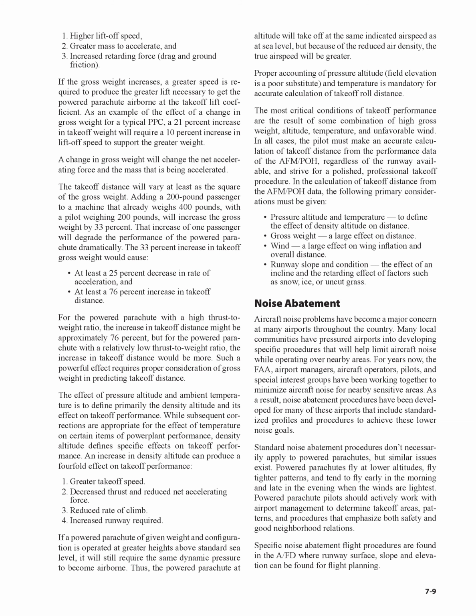roll distance. The most critical conditions of takeoff performance are the result of some combination of high gross weight, altitude, temperature, and unfavorable wind. In all cases, the pilot must make an accurate calculation of takeoff distance from the performance data of the AFM/POH, regardless of the runway available, and strive for a polished, professional takeoff procedure.